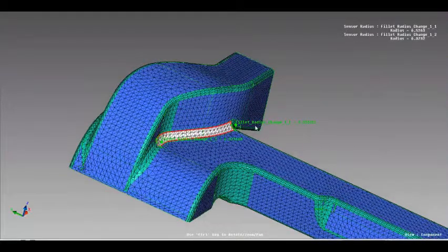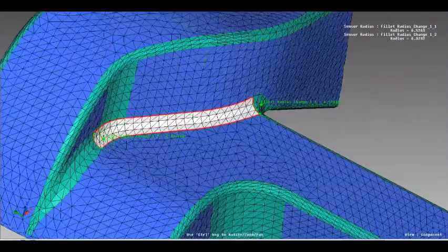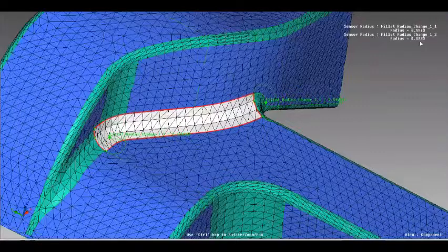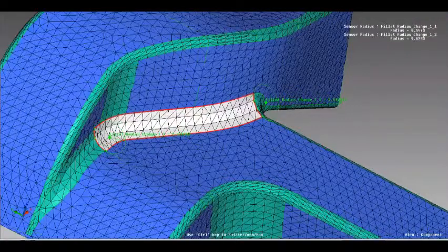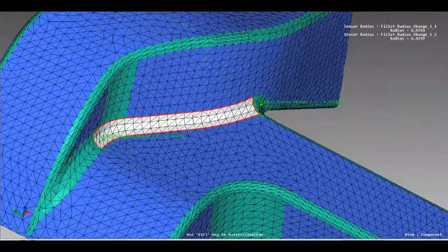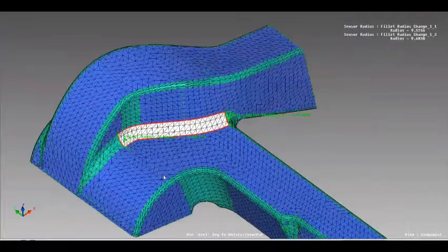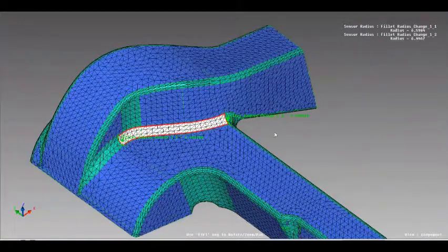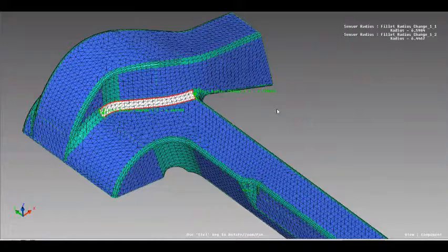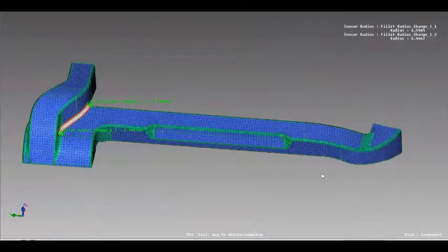When you review the parameters, the graphical representations change accordingly. This helps in optimizing the models for any flow analysis, and it saves a lot of time, and a user doesn't need any expertise in doing this parameter creation and morph set creation. So this is all about the auto parameterization of components.